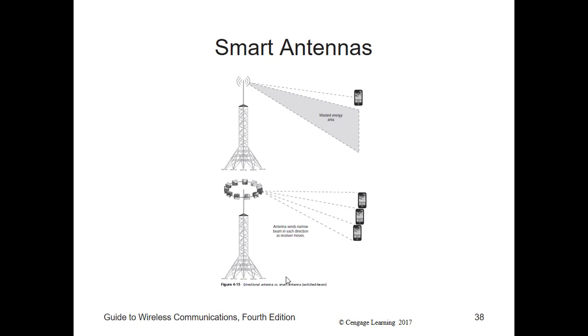There's also an adaptive or phased array antenna. It's similar to a patch antenna, but instead of being just a single piece of metal, it's divided into a matrix of radiating elements. So a computer-based signal processor will control the circuits in the antenna system, turning elements of the matrix on or off, as well as adjusting the phase of the transmission signal supplied to each one as the mobile user moves across the front of the antenna. This has the effect of sending an energy beam in a particular direction and is sometimes called beam forming.